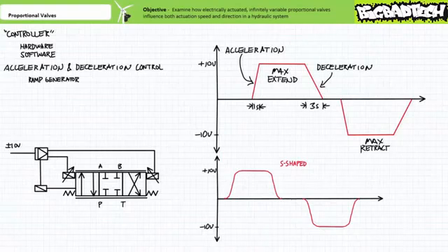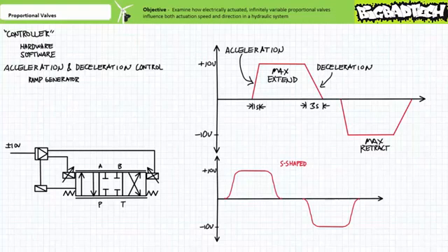Controllers need not limit themselves to linear slopes. One can also generate something often called an S-shaped profile for obvious reasons. An S-shaped acceleration or deceleration profile might be equivalent to a dead stop, to slow stroll, to run, to sprint, skipping some of the intermediate transitions if you get what I'm saying. An example of an S-shaped acceleration-deceleration curve might be the feeling you get when an elevator starts and stops.